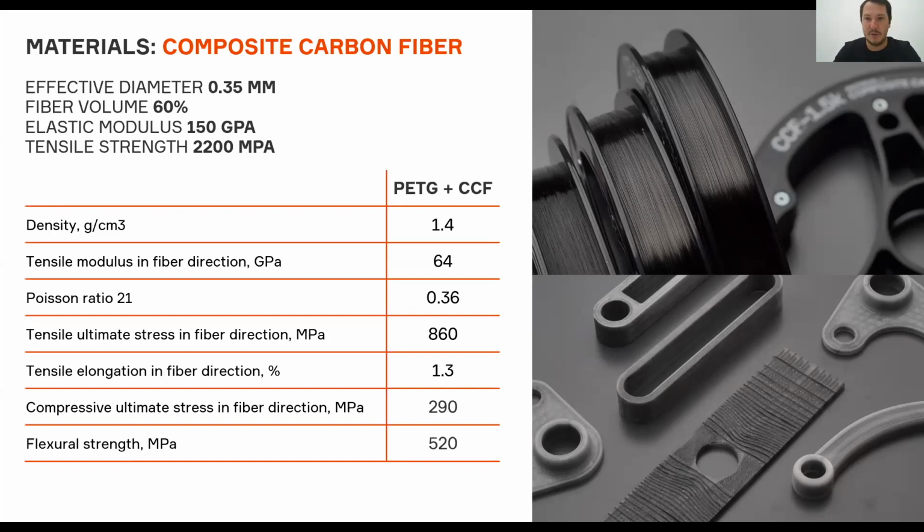It could provide some improved adhesion, and it could provide some improvement in interlaminar properties of the composite material, but it also can have some difficulties. So it's quite important for good processability and for good printability that the co-extrusion plastic has low viscosity.